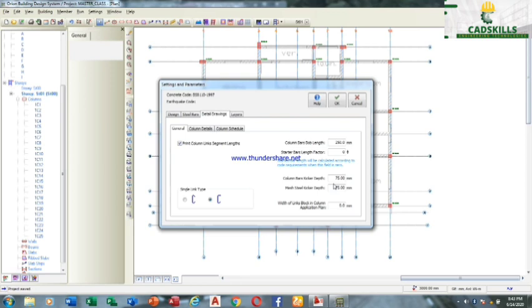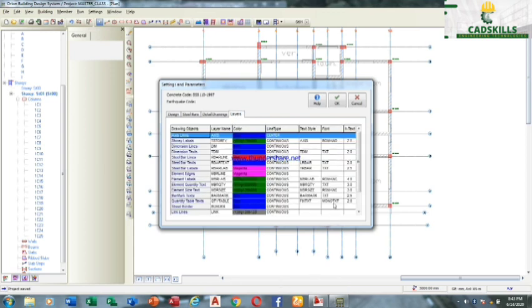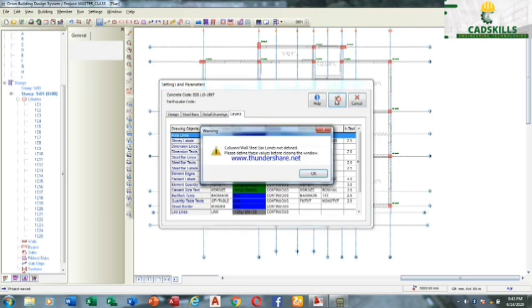As you're casting your starter bars, your columns, it should be above the normal floor level by 75, so that the mass concrete coming should not be able to breach the strength of that concrete. Is that okay? All right, you can change your layers, color, line, and all the rest. That is for column.